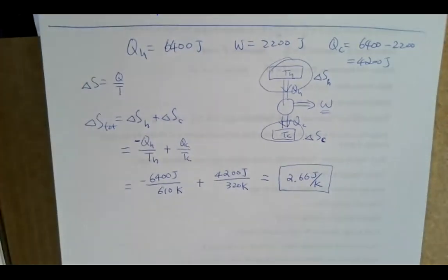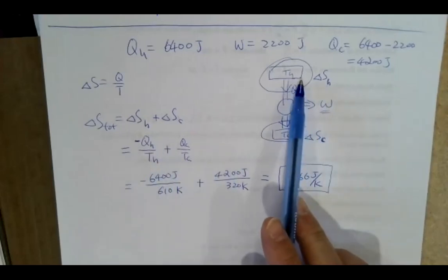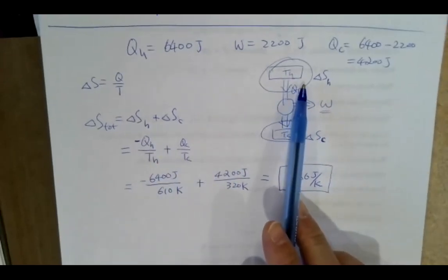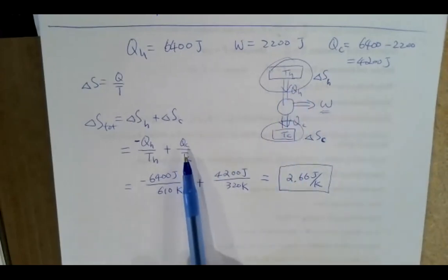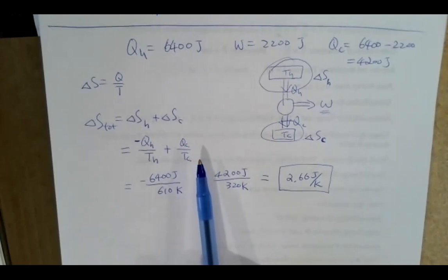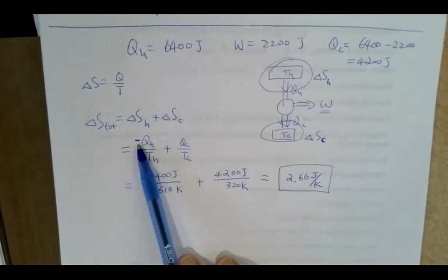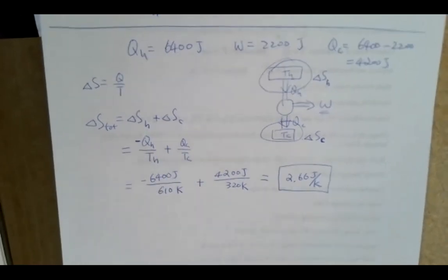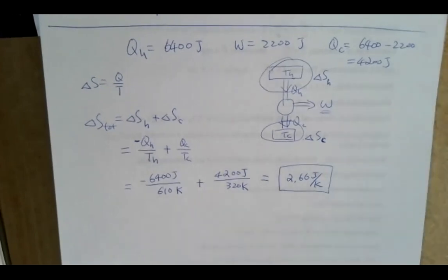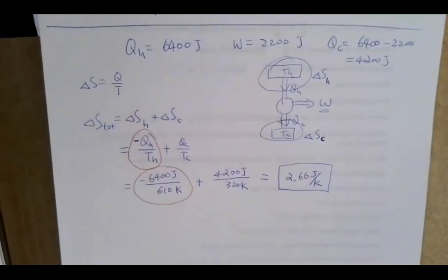Here's something you want to pay attention to: the signs for the heat. When we talk about just the engine and calculate the efficiency, we actually don't care about the sign. But when you are doing the entropy change, that means change in Q over T, that means the change in heat. So you want to put the appropriate sign. That guy is negative Q there. Just want to highlight that.